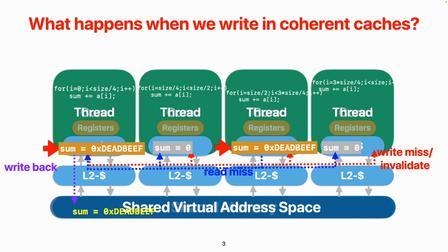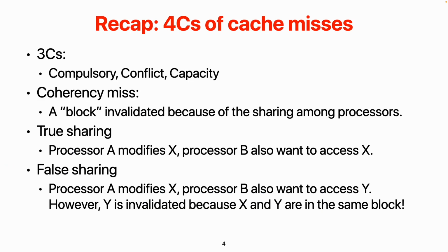However, the key of using thread level parallelism to speed up a single program is to multi-thread your program. To maintain the correctness of your program, we still need some kind of underlying hardware support, for example, the coherence protocol and consistency protocol, to make sure that at least the programmer can predict to some degree what's going to happen. However, even with that, there are still issues that we need to be really careful about when we partition our tasks.